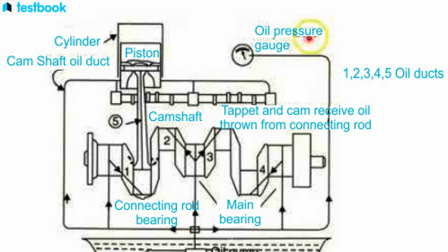Another advantage is that the engine height can be reduced, thereby increasing ground clearance or lowering the center of mass. With this arrangement of the lubrication system, fluid consumption is reduced, and the original performance characteristics of the engine oil are less susceptible to change, i.e., the oil gets a longer service life before routine replacement.